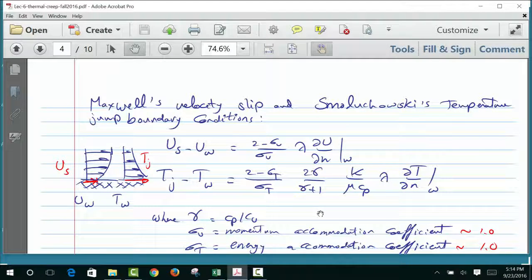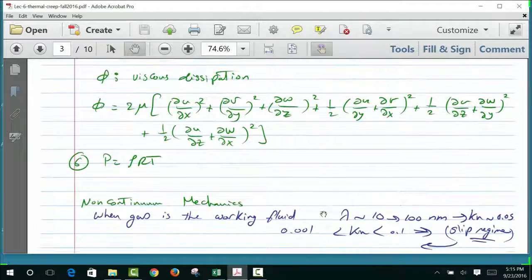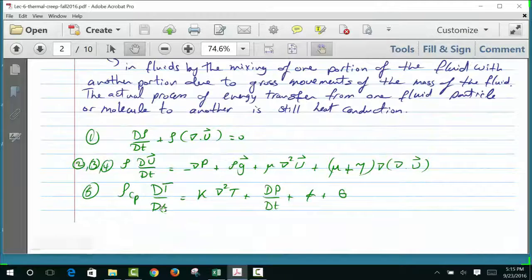We just solved the velocity equation, or the Navier-Stokes equation, and realized that you actually have a slip in the velocity at the wall. So similarly, if I give you that energy equation, and I ask you to integrate it to come up with the temperature profile in a channel, you need, like with any differential equation, boundary conditions. Say the upper plate is at 100 degrees and the lower plate is 50 degrees, and tell me the temperature profile.